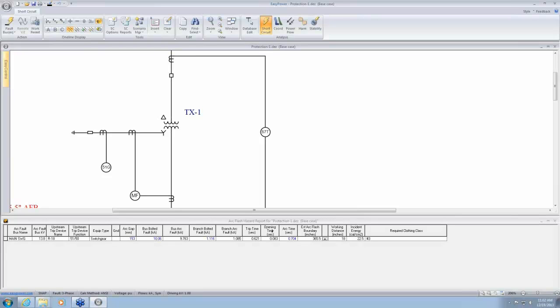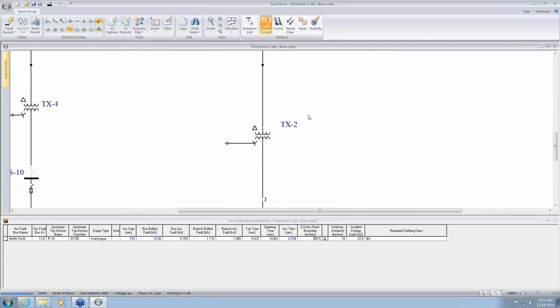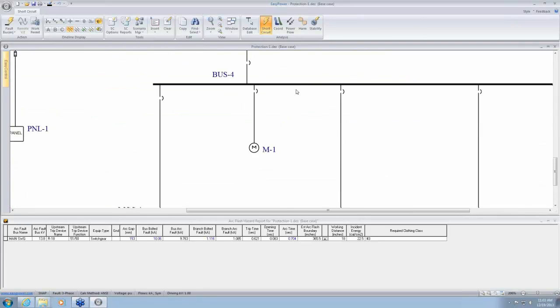Now, TCCs or time current curves that are published for low voltage breakers, the breaker opening time, the contact parting time, is included there in that TCC curve. So that is the maximum clearing time. So when we have low voltage breakers tripping, see the trip time is blank because you do not need to, sorry, I chose the wrong bus.